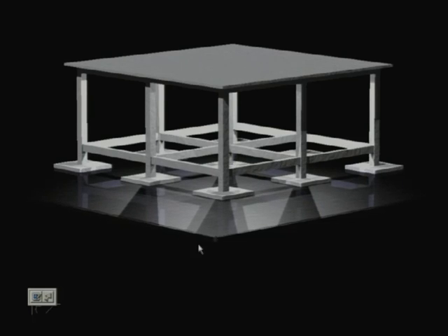We have started from the bottom, but when we shall design we do it the other way, we start from the top. So, slab, then beam, then column, then tie, then footing. So, this is how the design will go. Even if you have a staircase, the staircase has to be designed first. So, this is just one schematic.